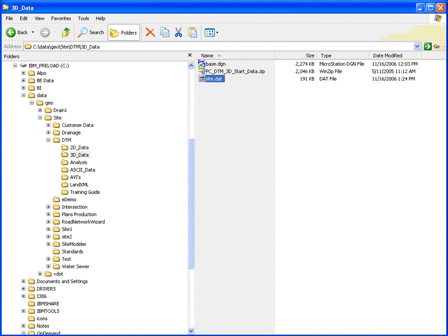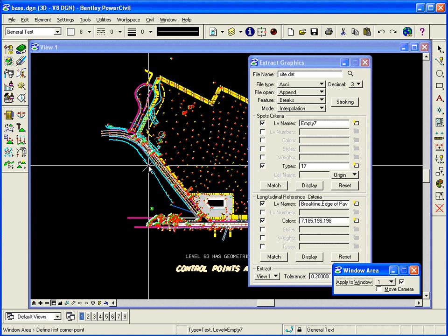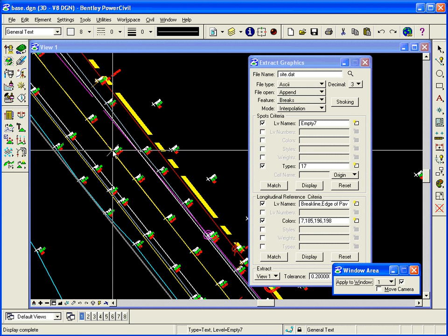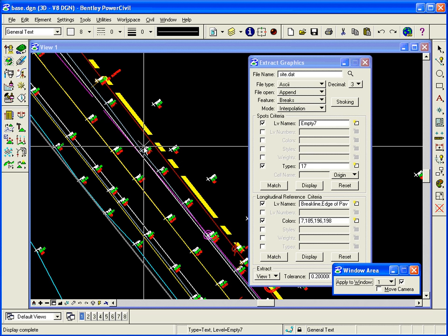So you can see that we can take three-dimensional data, bring it in to a DAT file, simply just reading the XYZ, or two-dimensional data by going through a particular line, for example the center line, reading the elevation from the spot nearest the line, but getting the XY from the line itself. And that concludes the DAT file. Next we'll look at building the TIN from this information.